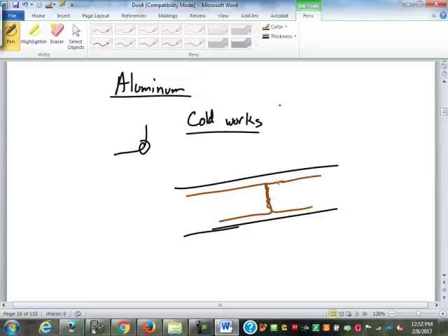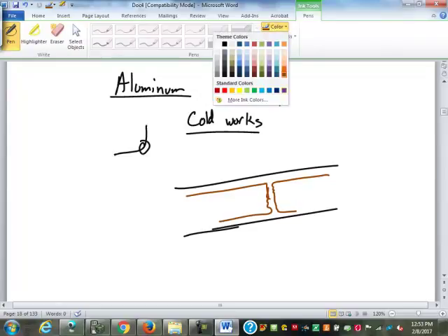And when there's a little crack in the wire like that, now I'm going to exaggerate it for a second here. Well, now there's a mess with the conductivity. You have like a transmission loss or whatever, because even if they are staying tight together, you're still going from one contact to another. It's like having a splice in it. And yes, it has a higher resistance, and when there's a higher resistance, it creates what?